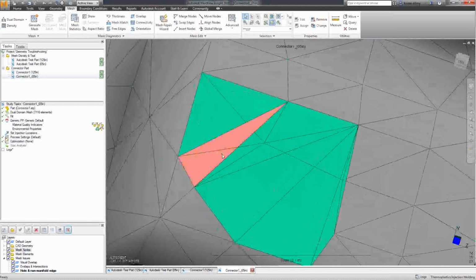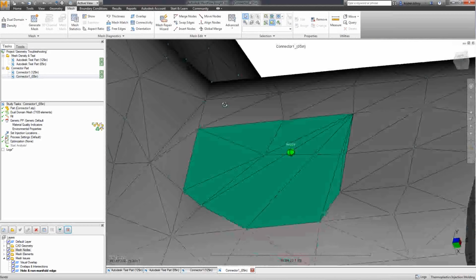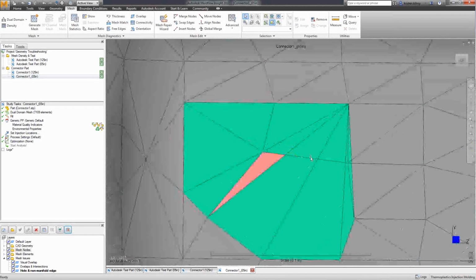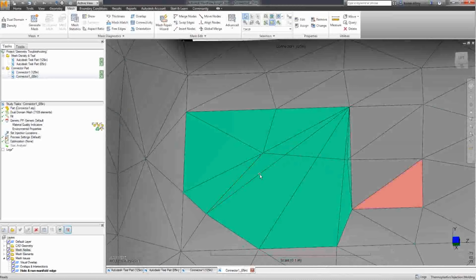And it looks like there's clear overlap there that's really causing some issues. So typically what I like to do, I just click delete, and that looks like it basically resolved that there. But we still see this line going across here. Now, it doesn't look like it's too bad, but you can see here that this isn't a triangle, so it's not a true element. The element is actually going up here, so this one is overlapping those ones there. To resolve that, what I would probably do is, again, I might just delete one of these.